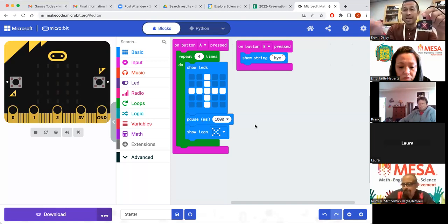So if you shine light on an LED, it gives off just a tiny bit of electricity. And so that means these LEDs can be used as a light sensor. The more light that's shown onto this grid of LEDs, the more electricity is being created. And so you can measure how much light there is depending on how much electricity is created from these LEDs.